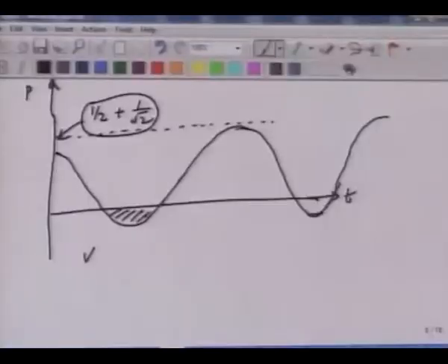The other thing is that the peak value can shift because of the presence of inductors and capacitors, or elements in the circuit similar to inductors and capacitors. And the third thing, which has a strong bearing especially in the electrical domain, is this term V over Z, where V is voltage and Z is the total impedance, which influences the total current.